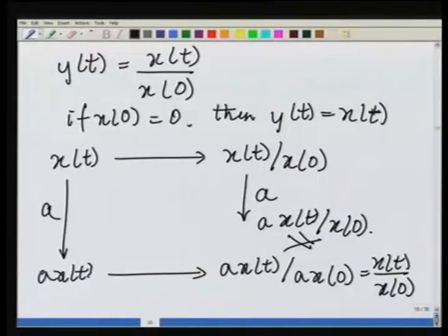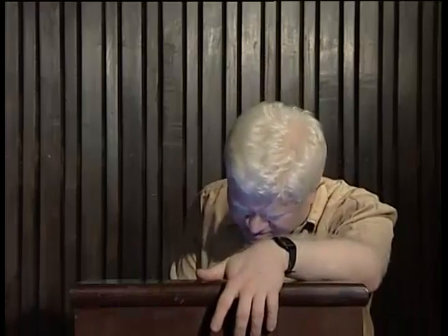We have just completed our exercise for only homogeneity for the case of systems where x(0) is non-zero. For that category of signals taken as inputs, we have found that the system is not homogeneous. Now, if we consider the other class of signals, the class where x(0) is 0, then what do you think will happen? Then we will just make modifications in this very diagram.